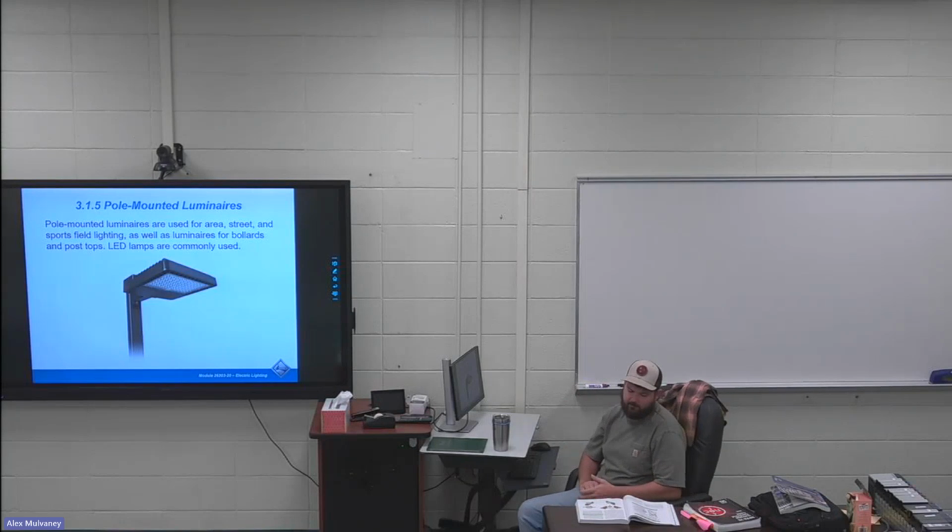So I've seen this done. Usually I'll just try to find a box that can support that amount of weight, or you actually string something through the box and you tie it to a rack or something like that. I've done, I think, all of one ceiling fan that somebody bought that had a large electrical motor. It looked like an airplane propeller type ceiling fan, but it was very heavy, and I had to run through the box and actually tie off to a roof rafter to hold that weight because the box was already installed. I couldn't easily change the box. It was easier to run my cables through and make sure it was secured.